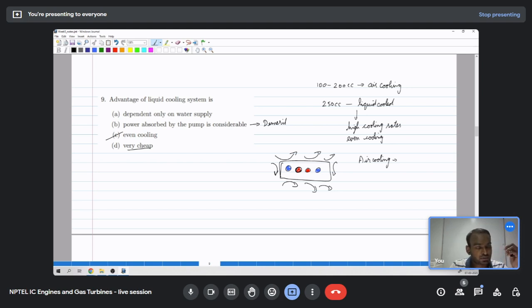And the other case is you will have cooling lines flowing from the engine to the radiator and so on. These can puncture, and then the coolant can leak. And the radiator itself is a very delicate component. You can see the radiator, even by touching the fins of the radiator it can get damaged. So the radiator is very sensitive to damage, and it is not so reliable.